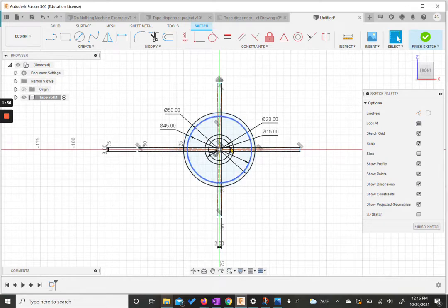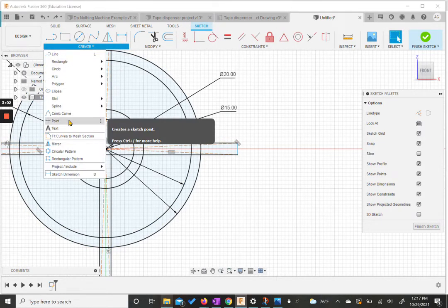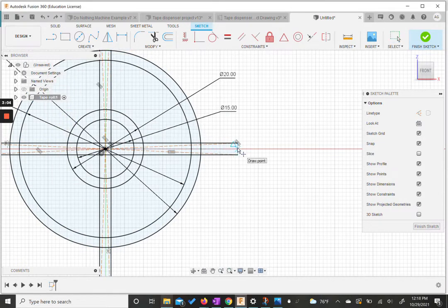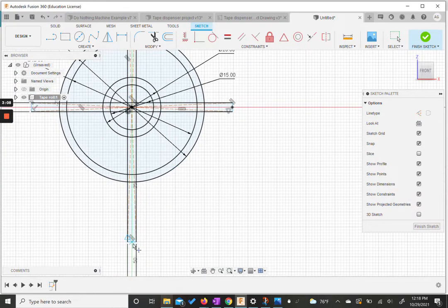All right, there's a couple different options for moving these lines from a rectangle closer to our circle. So the option that I'm going to do to get this rectangle to be the correct length where it connects to our outer circle, I'm actually going to go to create, grab the point tool, and put a point right in the middle of those short lines, at least on one end of our box.